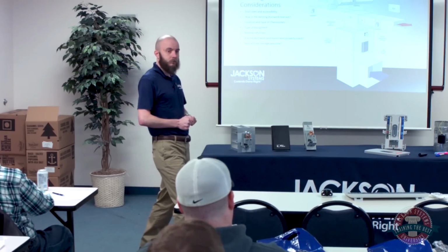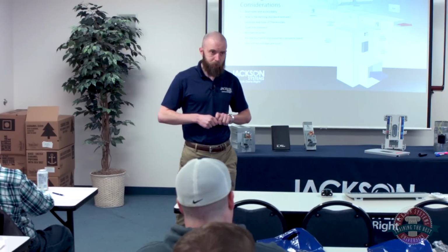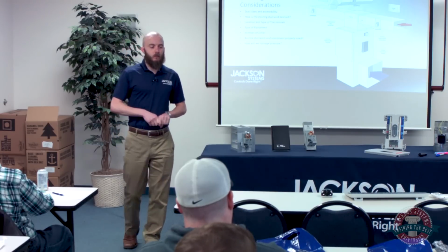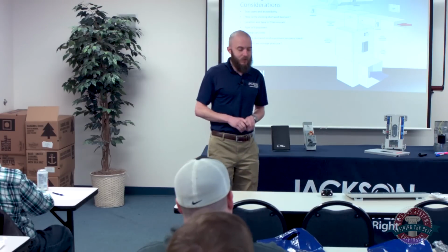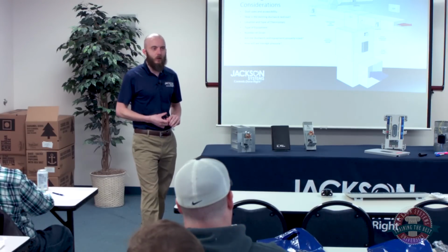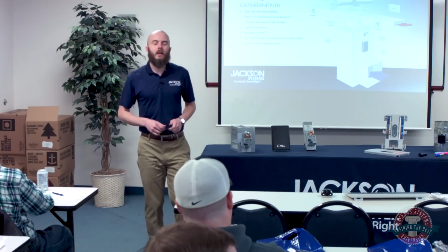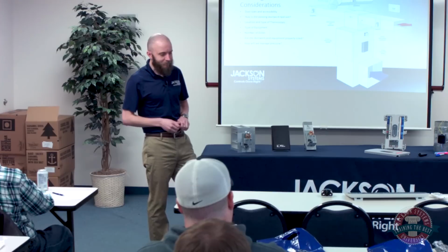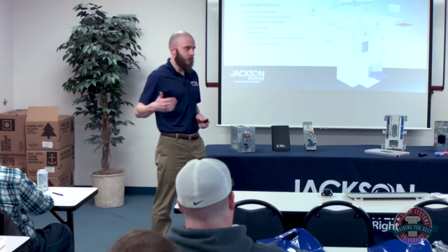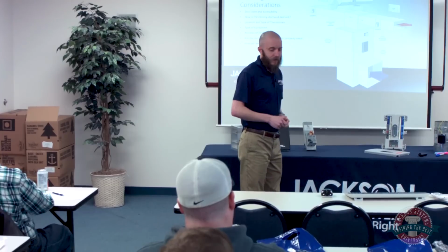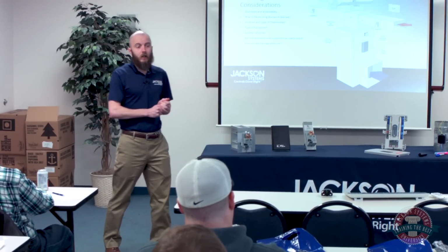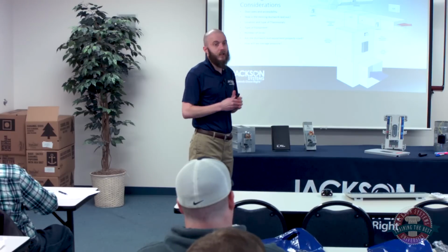Yes, sir? Variable speed blower motors, they affect this too, correct? Yes, they can. How do we adjust for that? Well, the question was about variable speed blower motors as to whether that will affect the system, and yes, it will, pressure-wise. So as we start closing off zones, you're going to get an increase in static pressure. Variable speed blowers, depending on how they're controlled, if they respond to static pressure, then yes, they would respond to closing off dampers.